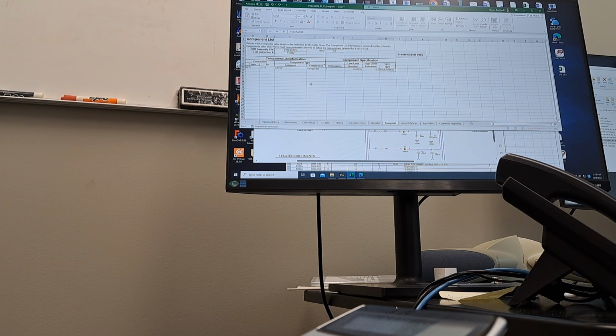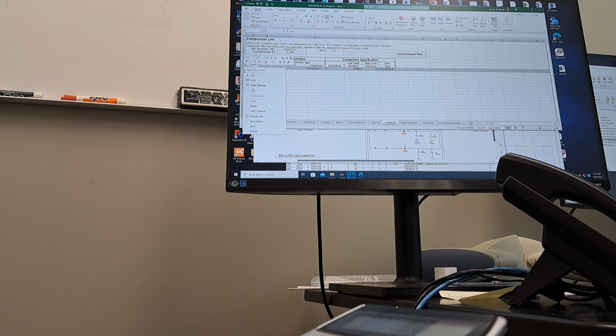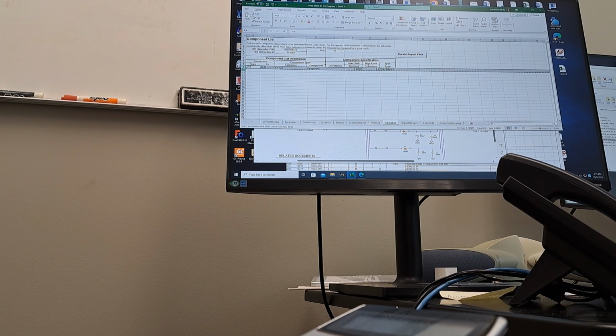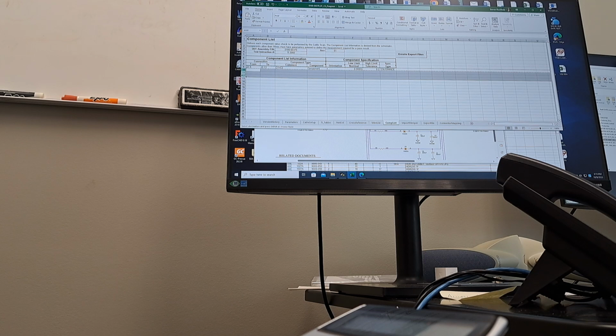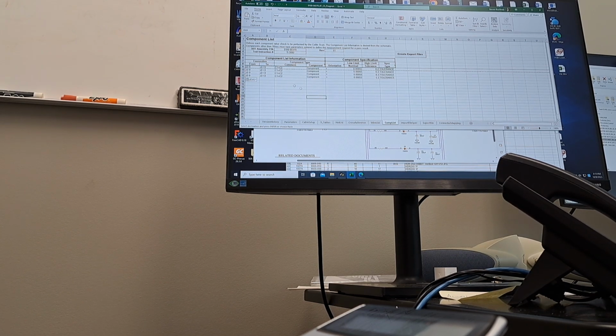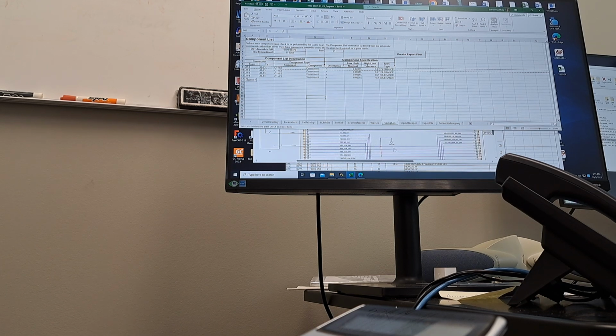And then we're going to create four capacitors. So this one's going to be pretty easy. So we say copy, paste. Okay, so now J2 13 is going to be the same for all of them, but then the other ones are going to be J2 9, 10, 11, and 12.